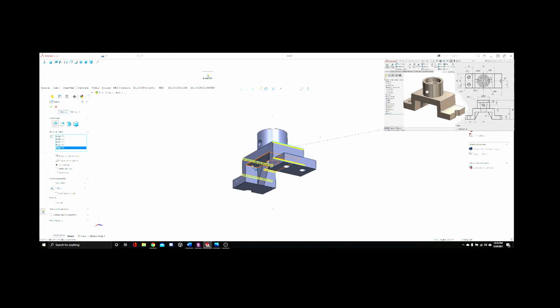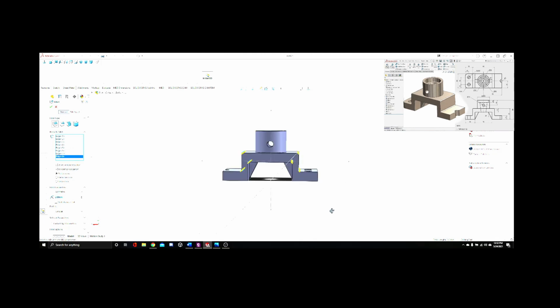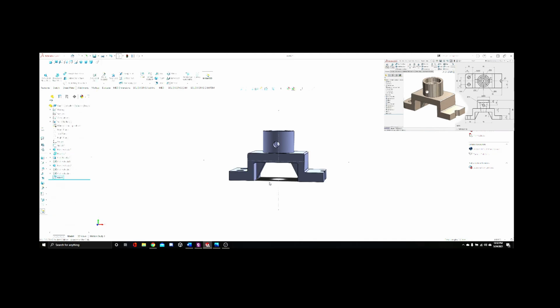And since we drew that diagonal across, you need to come over and get the other line on the other side. That line right there. And based on the drawing, they don't actually give us that value on the sketch, but that looks pretty close. And so we can say, okay. All right, see? So now we've got the fillets on our corners there, and now we want to round over these two corners as well. Now these, they actually give us a value for.